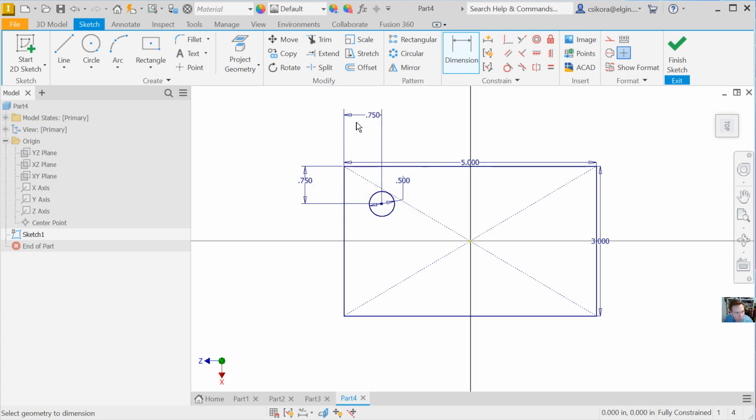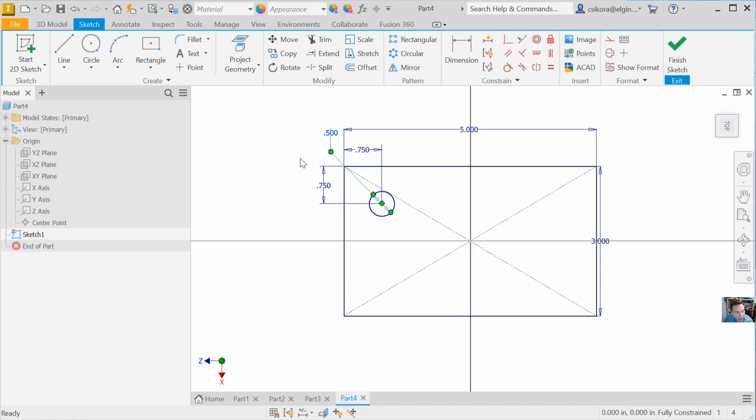Now, those of you who might not have had an actual drawing class on how to lay out a drawing, beware: you try to center the dimensions as much as possible like this and get the larger dimensions up above the smaller ones, and pull out any of these other dimensions that appear. And you try not to overlap the lines too often. Okay, make it look nice that way. Just like goalposts, if you're trying to hit it in a soccer game, you shoot for the center.